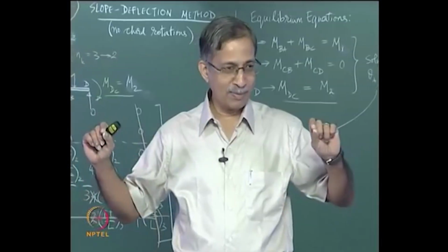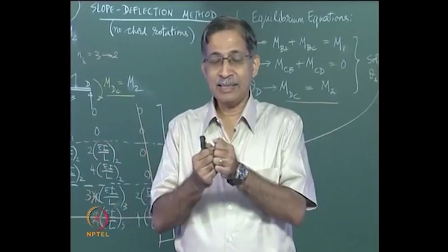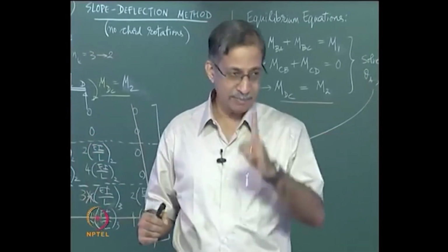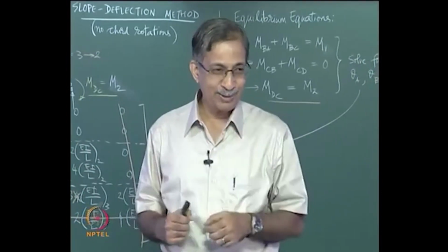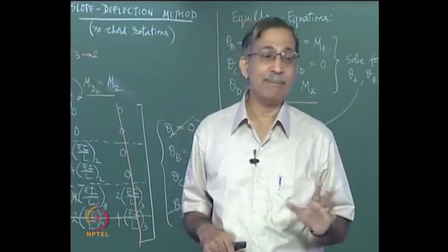Now at B we don't have any roller support kind of thing. Let me ask you, when you had the continuous beam you had no problem. In the continuous beam you had a reaction at B, a vertical one; here also you have that, it is AB which is taking it. So AB is referred to as a beam column.